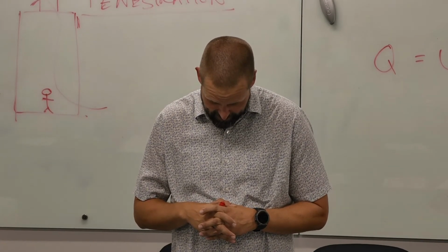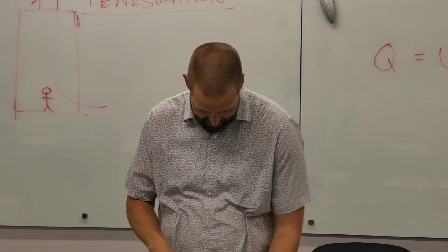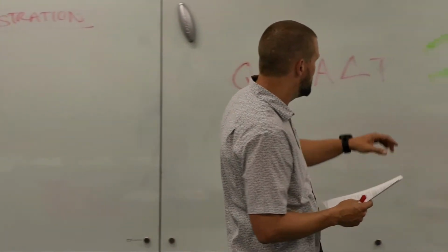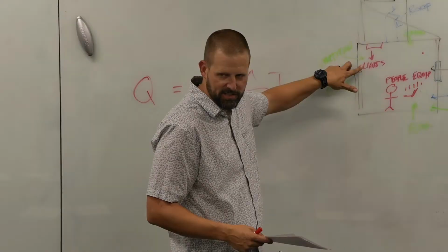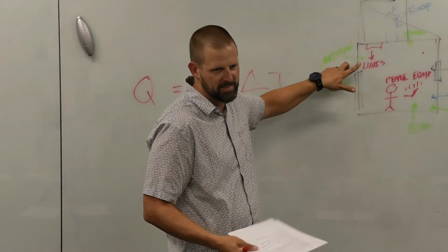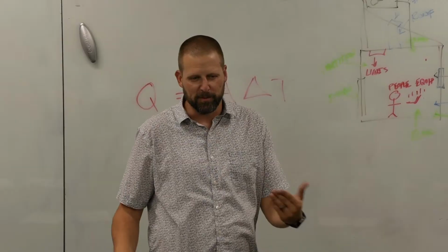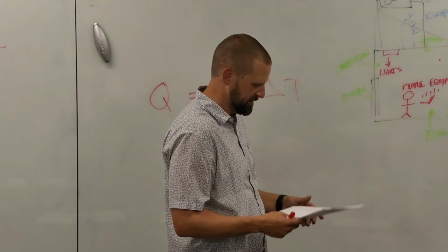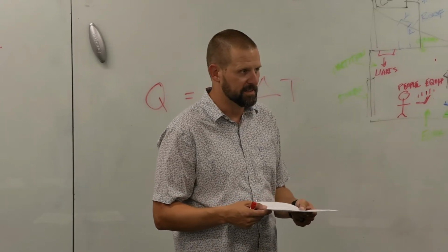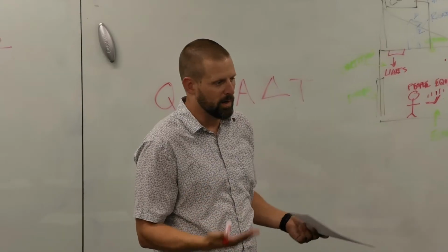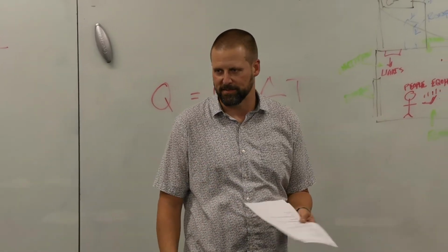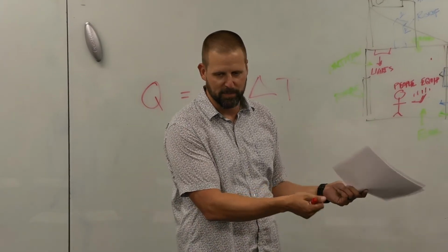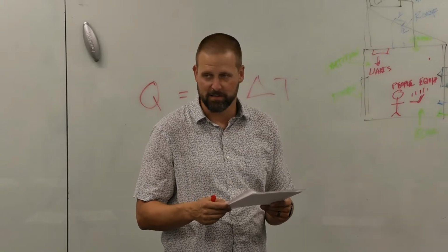Okay, so let's talk through the other stuff on here that we haven't covered. Partitions: we generally don't account for partition differences indoors. Even if we set the thermostat differently, we're not going to put that on a load. We assume they're all at a certain space. Though if you see something wildly different, like a steam boiler room next to a critical temperature space, you might want to account for the load across that wall or ask for insulation.